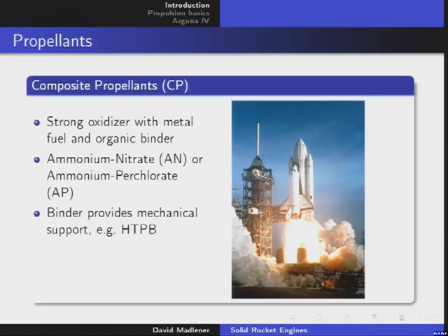But you have to be very thorough at production to not introduce bubbles, because every bubble is like a crack, an increase in surface when the burning front goes through. So in this moment you produce locally more gas, the pressure rises, and you produce more gas, and it is of course a deadly cycle.